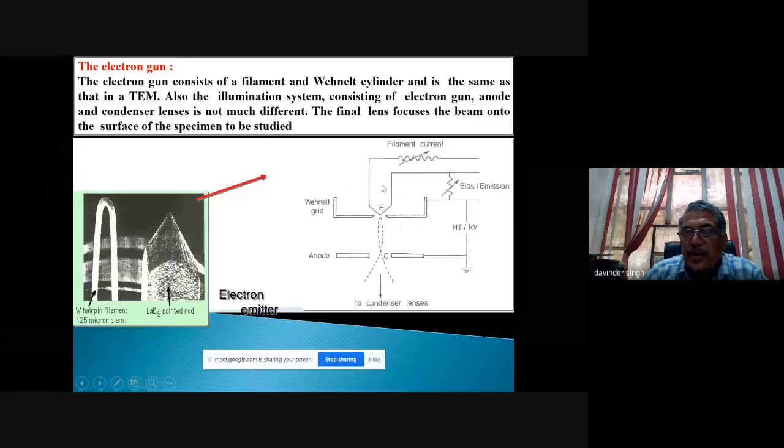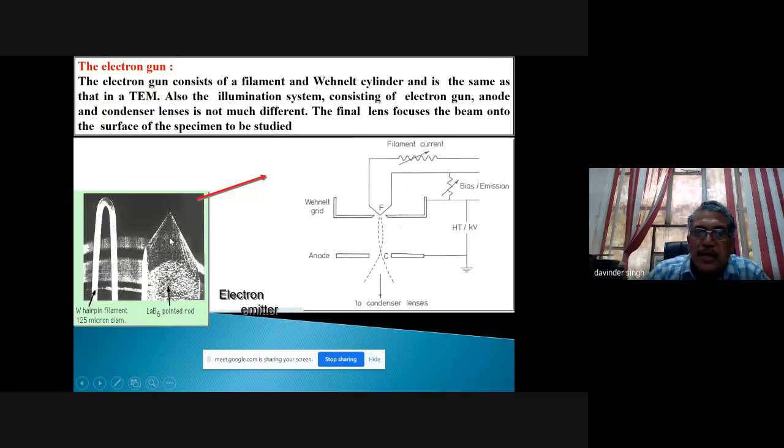It means that is how you are getting the beam current, depending on what type of gun source you have. Sometimes it is the pin type, sometimes a very sharp tip type of gun material you have, and you are getting the electrons, and then you are controlling with the cylindrical shape of that gun, and you control with the lenses or anodes, you can say.